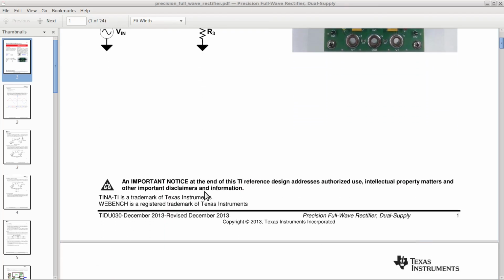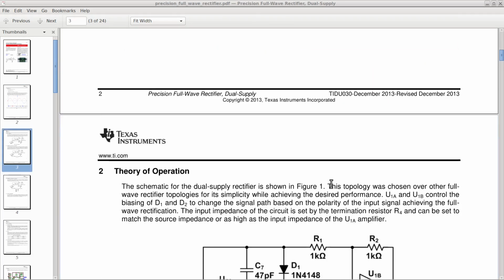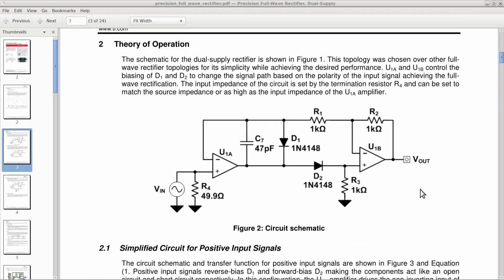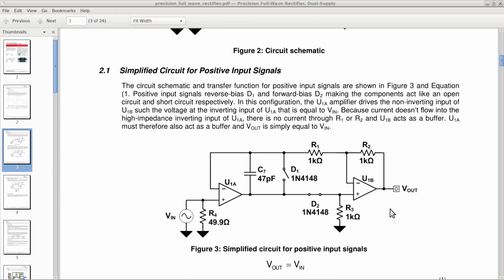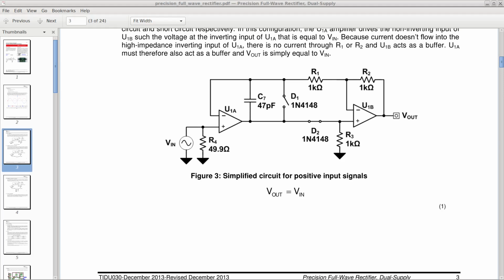Here is their technical article. The circuit is designed such that the two diodes effectively create a full wave rectifier from the positive and the inverted negative half waves of the input signal. The connections are configured to pre-bias the diodes close to their forward voltage threshold, and this ensures that even a minimal input voltage will cause them to conduct immediately, which is exactly what we need for accurate low voltage measurements. I will provide a link to this paper in the archive available on my website, eleneasy.com, for those interested in understanding the detailed operations of this circuit.